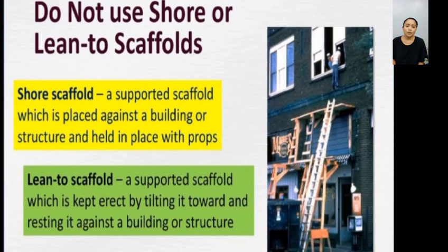Do not use shore or lean-to scaffolds. Shore scaffold: a supported scaffold which is placed against a building or structure and held in place with props. Lean-to scaffold: a supported scaffold which is kept erect by tilting it toward and resting it against a building or structure.